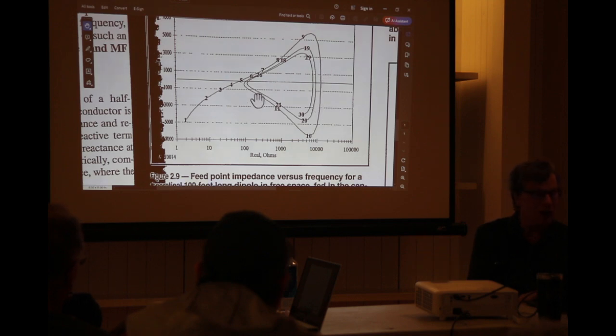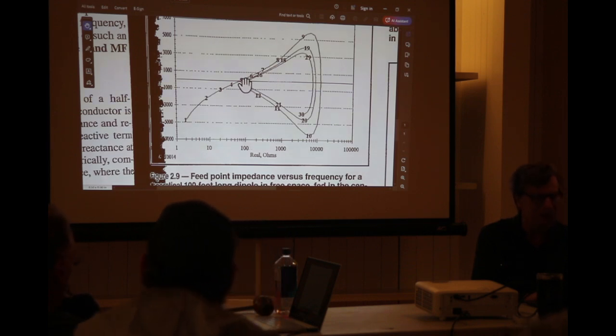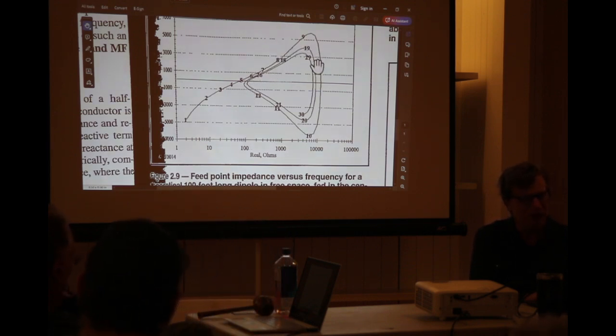Now in the third harmonic, this is why a 40 meter antenna works on 15, right? Because once again, we're at third harmonic and we have a rather gradual increase and we have a normal series resonant mode and the impedance is reasonable here. And then as we go to the fourth harmonic here, again, we have this precipitous change of reactance between here and here.